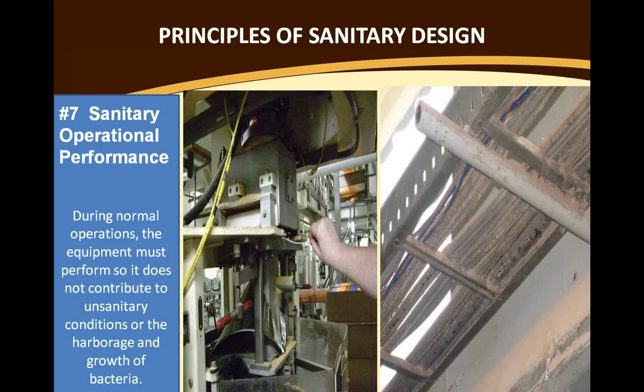Make sure that we have adequate floor clearance. Exhaust systems: if you have exhaust systems, make sure there's a clear separation of raw and ready-to-eat exhaust systems. Buttons and control switches that are cleanable, not just simply covered with a plastic bag. Avoid product buildup on utility runs, and as the picture on the right shows, position your utility runs definitely away from exposed product. Utility runs and races are extremely difficult, if not sometimes impossible, to clean.